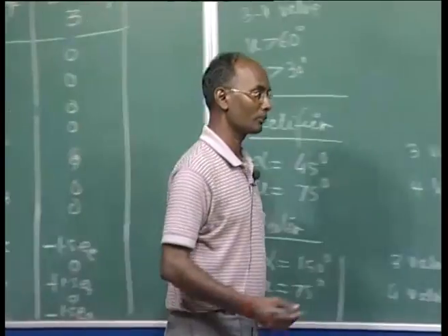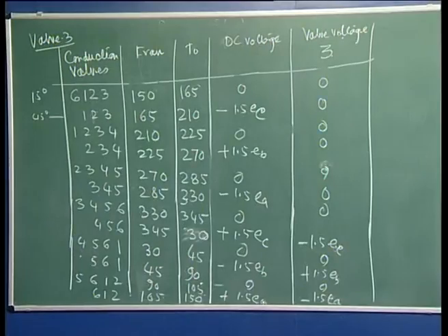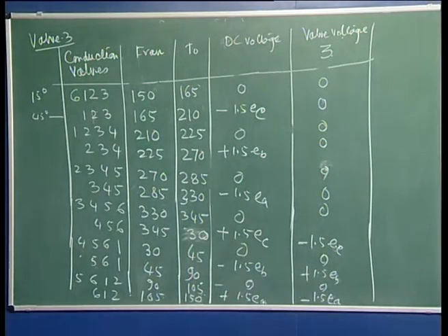So I can draw the valve output voltage here directly, and again we can start from here, that is the 3, and it is going all the way up to when the 6 is getting pulse, means it is going to be 0 here up to this is valve voltage, and even though 2, 3, 4, 6 are conducting, it is 0.